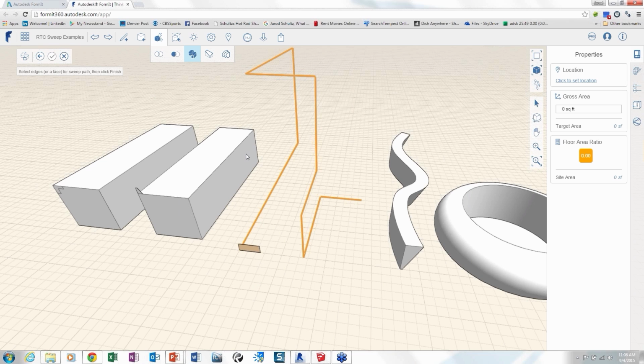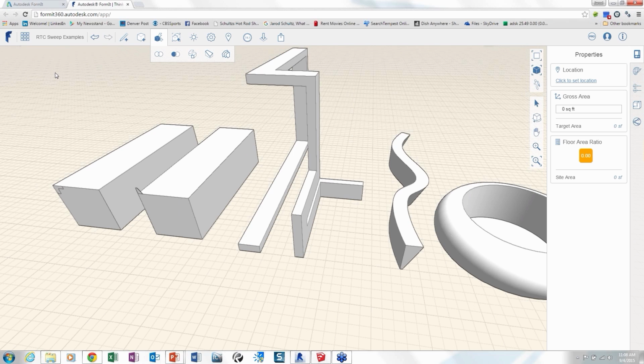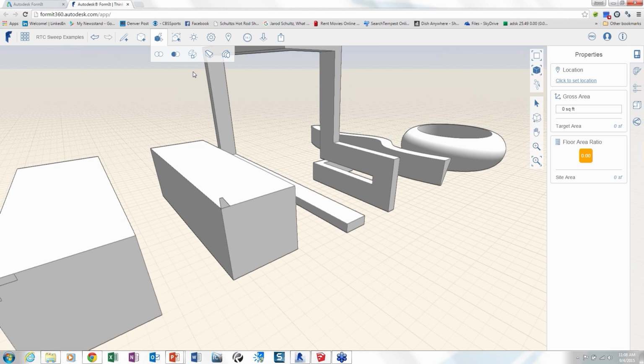Here's what I know will work. So go into Sweep, pick the profile, and now hover over one of those edges and hit Tab. The magic tab key. And select all connected. So just like in Revit. But that's a good point about double-click. We should take a look at that, because probably what it did was it selected the original profile that it was connected to, and that probably confused it. Yeah. Cool.